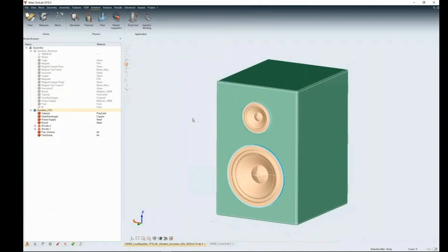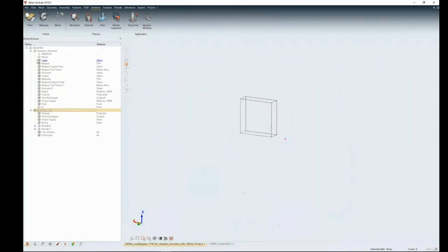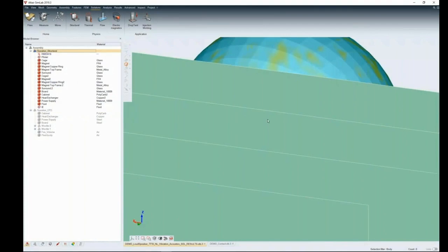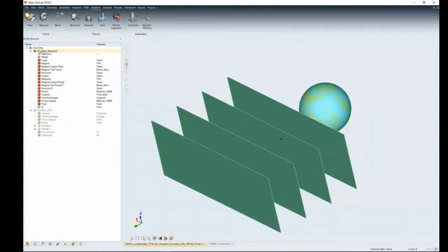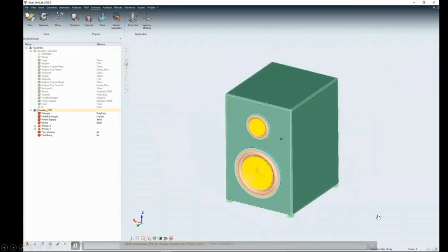Now, after making sure the assembly is set and you have all those parts, here you're looking at the left side, which is a model browser. So I have two sets of models for this particular simulation, and one is the structural assembly and another one is the CFD. The common parts are there between both of them, and the non-common ones are the ones which needed more attention in terms of the mesh. Now you saw that, that was the acoustic ball and the plotted elements. Now we'll come to that.